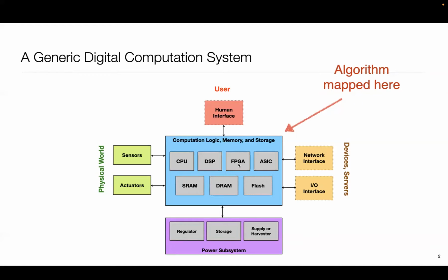And from MATLAB, you can go to CPU, you can go to DSP, you can go to FPGA, you can go to ASIC. It's a single entry point from which you can go to a lot of these places. Even languages like C or C++ or Python, there are restricted subsets of them, which you can map to the hardware also. So the view I want you to take away is that there's just a spectrum of choice, right? I mean, totally hardware to flexible hardware to specialized processors to more general purpose processors. And these are just 4 points. There are probably many, many others.